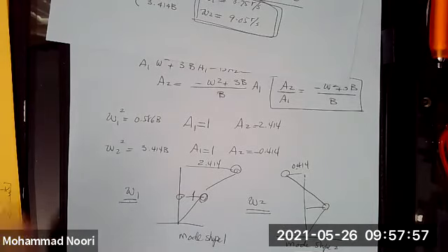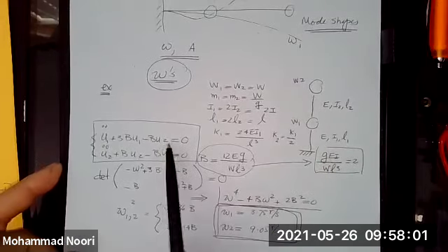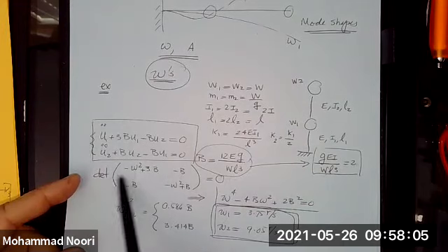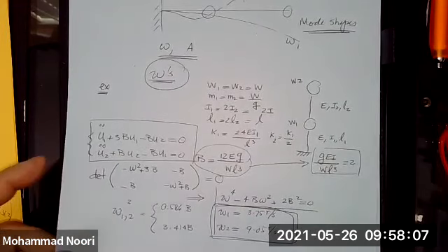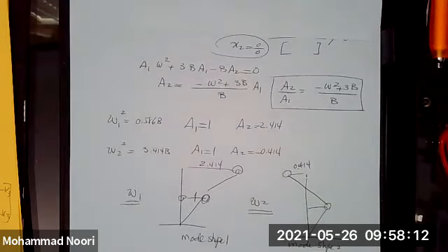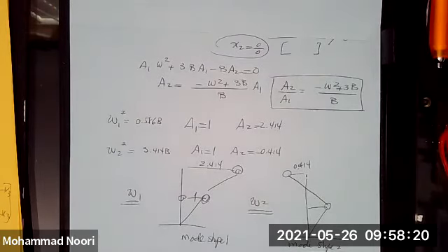You cannot do it yet. That requires transforming these equations into a different coordinate system. We'll talk about that. Find U1 and U2 there, find the displacement there, and transform them back into this coordinate system. We call those modal coordinates.